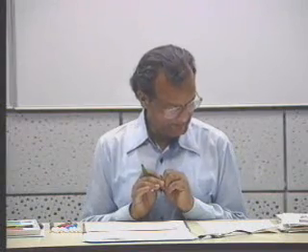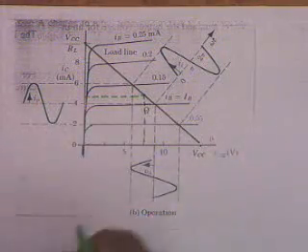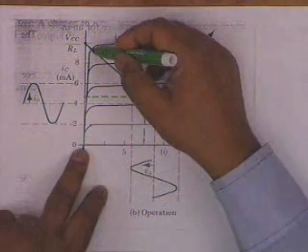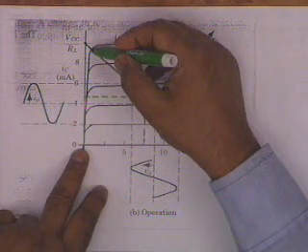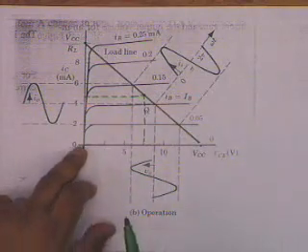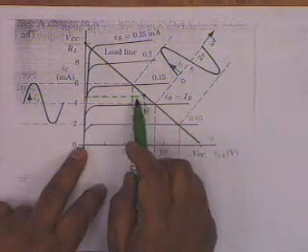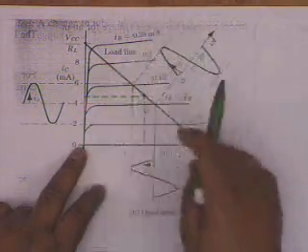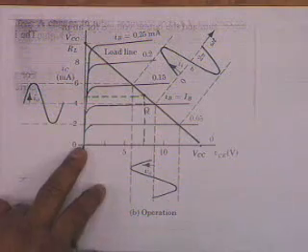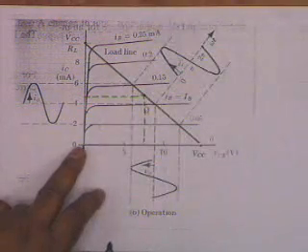And if the collector current is to swing from, let's say, 0 to 9.5 milliampere, which is approximately here, what is the corresponding base current swing? You see? These are things which have to be read from here. How much? This is obvious, it's given. 0 to 0.25 milliampere base current swing.